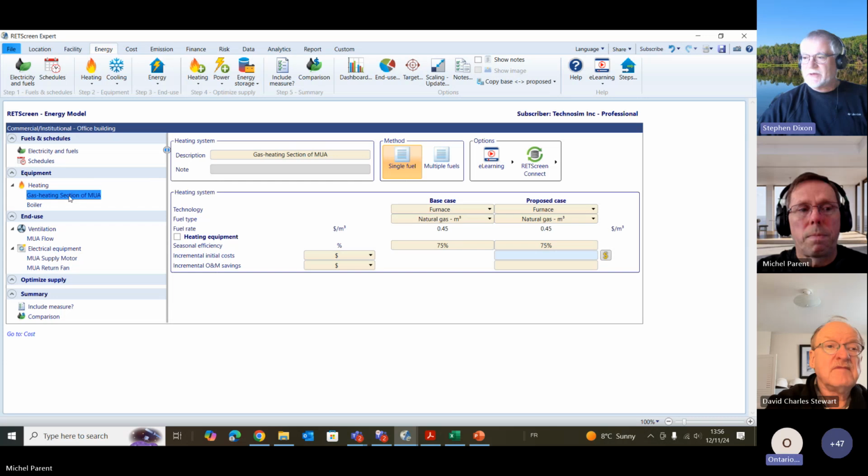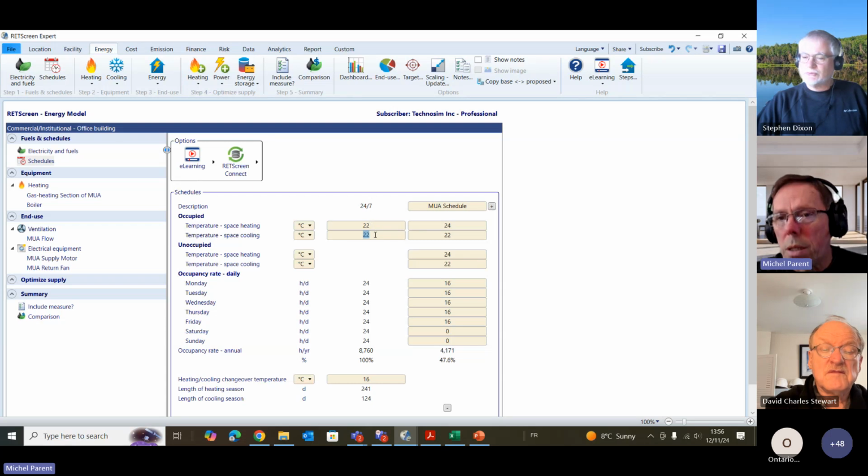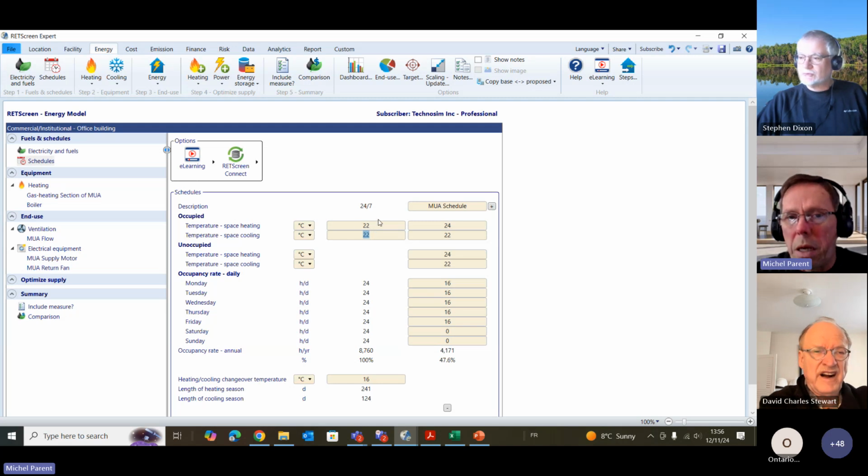Now I could try. Yes, I've answered that question. Oh, okay. The one about the temperature: we're using 22, not 24. Why? Because I'm not using that schedule right now. So I'm using 22 and 22. It's a recirc system, single zone, constant volume. You enter the temperature as they are in the space. The spaces are maintained at 22 degrees, so you enter 22. This schedule here, we'll delete it as soon as we can.